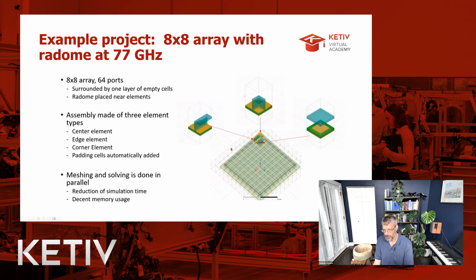As I mentioned, all of this is done in parallel. So the other important advantage in terms of meshing is each of these three different pieces can now be meshed in parallel and computed in parallel. And so this method of doing it this way, as opposed to explicit, enables you to utilize your HPC much more effectively. So you get a bigger speed boost using HPC when you use this 3D component methodology, because it lends itself to parallelization much easier, faster, and better.